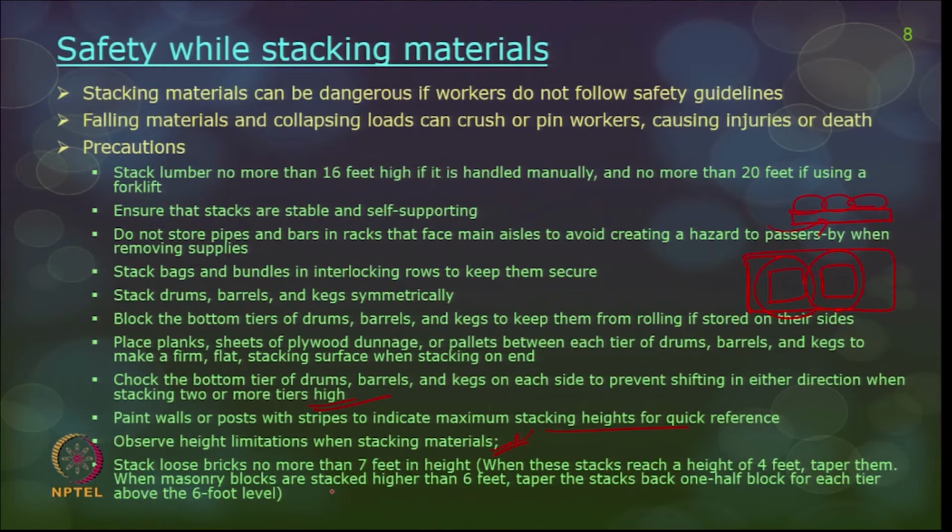And stack loose bricks not more than 7 feet high, and above 4 feet you should start tapering down. So, after 4 feet you should start tapering, leaving half a brick in width, so that it is not falling down and creating a struck-by hazard or fall hazard.